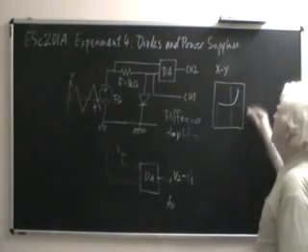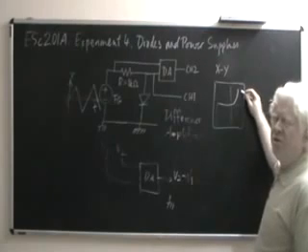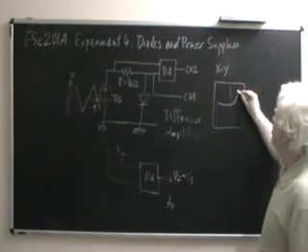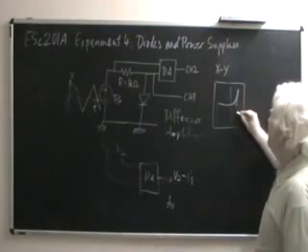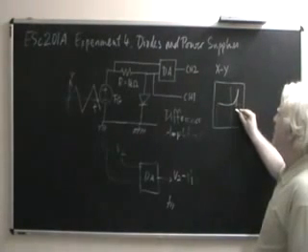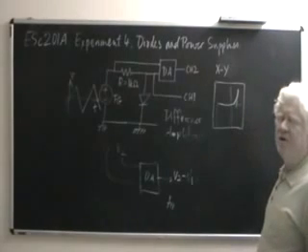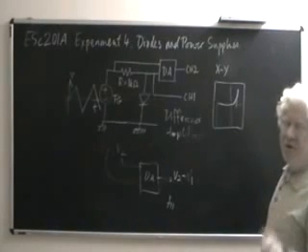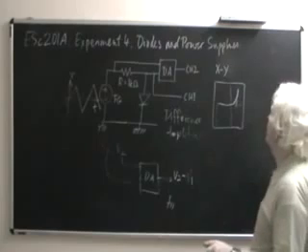and you can see the forward part. Now, it's already been explained, it's going to be explained to you that you take a tangent of this curve over here, see where it meets the V axis, and that gives you the cut-in voltage, V gamma. All that will be explained to you by the people who carry out the experiment.